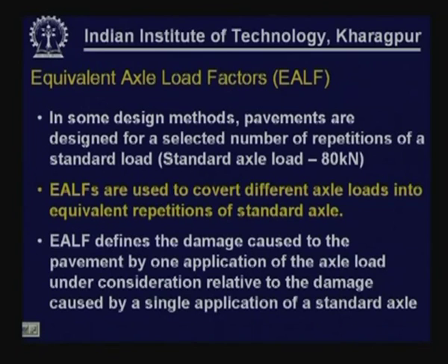If we are using the fixed vehicle concept, wherein we are talking about a fixed vehicle and converting the repetitions of all other vehicles into an equivalent number of repetitions of the fixed vehicle, we are going to make use of equivalent axle load factors.